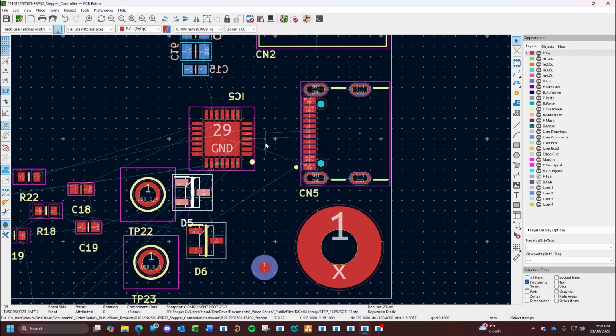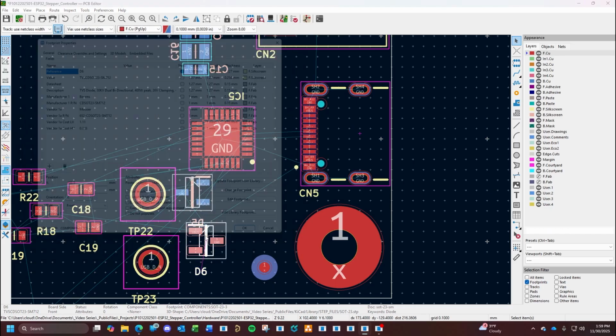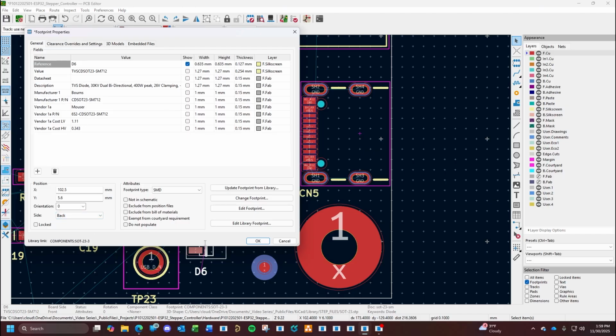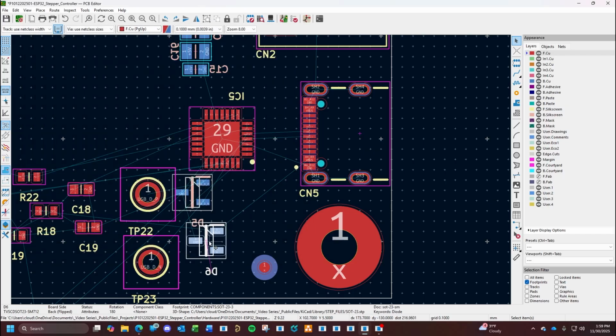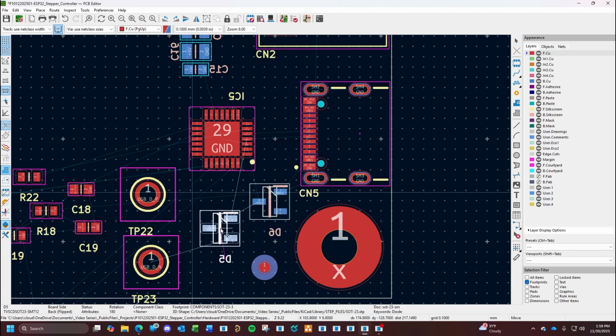We're going to have some vias in the USB bus. It's going to be unavoidable. So let's put these guys on the bottom, our TVS diodes. We're not technically moving data through them, so this guy's going on the bottom.